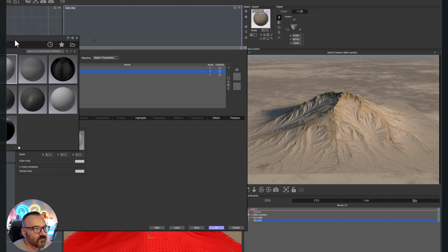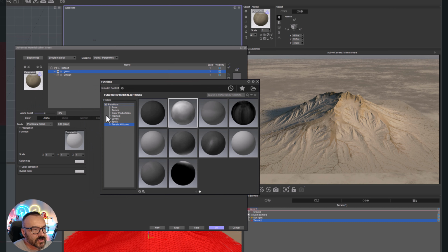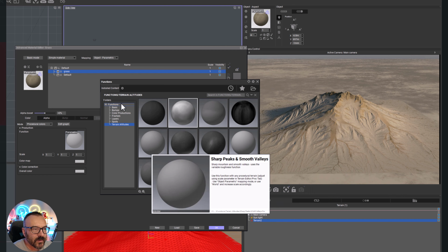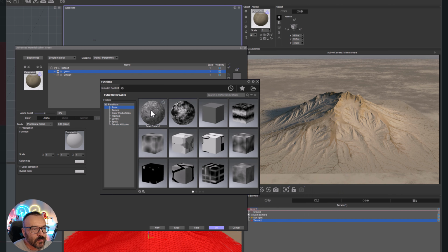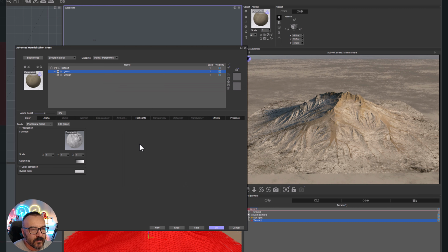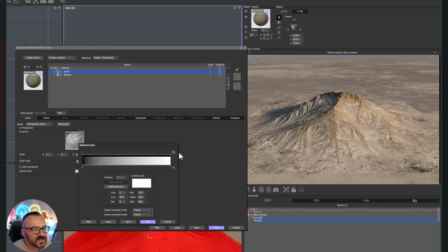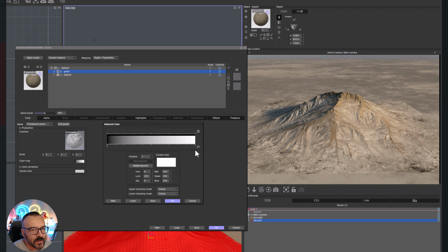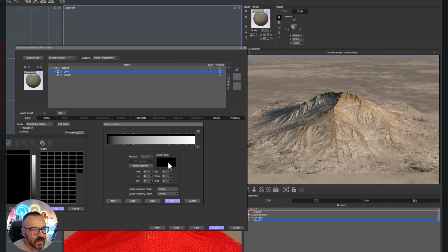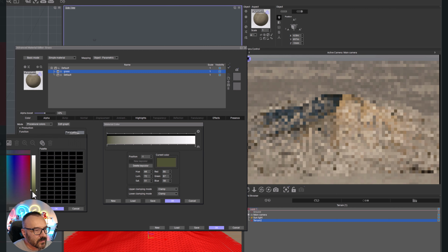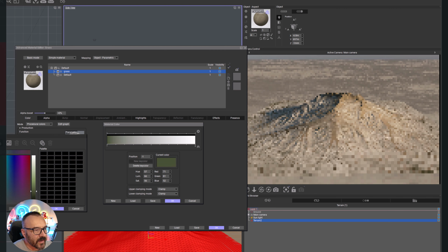Let's double tap click on our parametric function in this globe. It will open collections of different types of functions. If we go to basic, we can select one, terrain fractal. It will create a kind of interesting distribution, and it's utilizing this color map that we have below. So I'm going to color map, right click, and it says edit color map. Here we have a different coloring we can change by selecting current color, and in current color we can also go in and modify now.